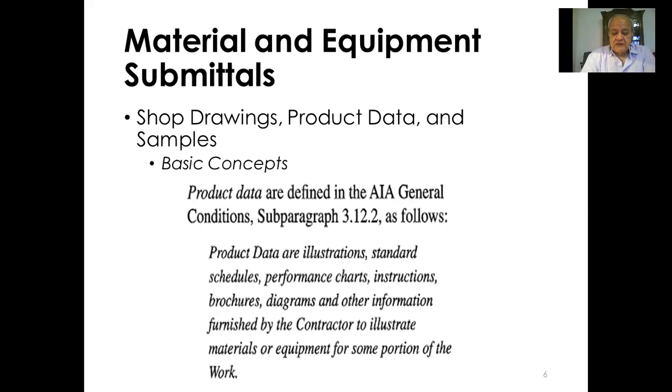Products: any product used in the site must be approved. You specified, for example, vinyl or carpet or tiles, or ceramic tiles in your drawings. There are hundreds of types of materials that can be used. You have to make sure that the material, its strength, its color, its size are what you want. And the contractor will provide you samples, so you select and approve one and sign.